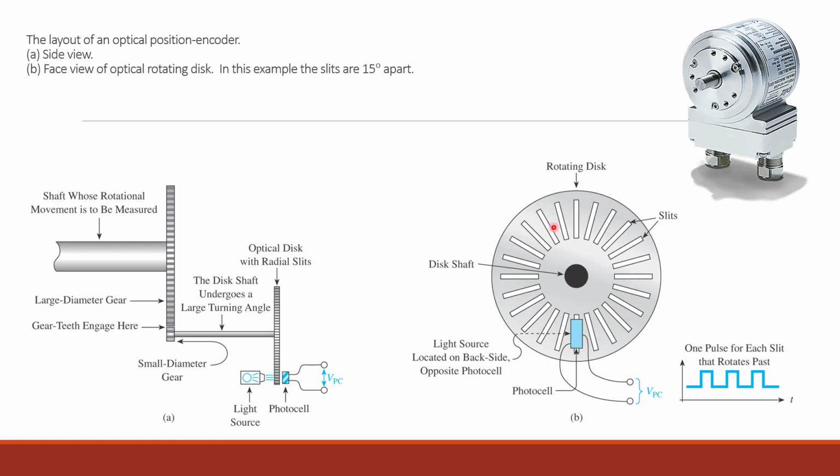And the way that it works is inside I have this wheel, and there are these slots all the way around it. Now there are not very many here, but in a typical encoder you could have maybe 600 of these. And note that the more of these that you have, the more you can zero in on how many degrees. So maybe there's 5 degrees between here and here, 5 degrees between here and here. So my limitation on accuracy or precision is limited to 5 degrees. If I had 600 of these, now I'm measuring fractions of degrees, so it's very precise.